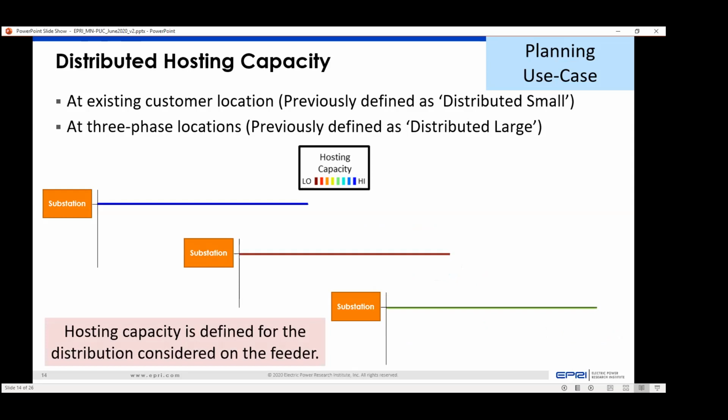And within Synergi, the distribution software platform, they have a similar assessment, and it's coined GROW, hosting capacity based off of a GROW assessment. That's why I'm trying to use consistent terminology across tools, where this is more of a GROW-based hosting capacity assessment versus a true stochastic-based assessment.